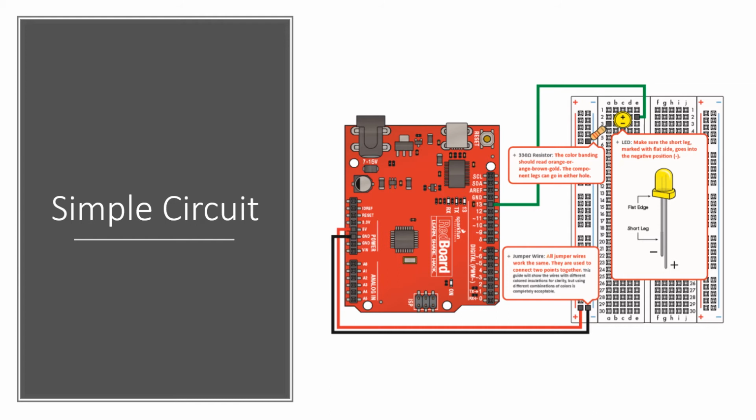All right, the power goes out through pin 13. Each of these is essentially a pin you can put wires into. I know from looking at the source code for the circuit that power comes out through 13. It comes up here through the green wire, and you see it's going into E2. And then this LED, remember, light emitting diode, is plus and minus. That one is in D1, so the power goes from E2 to D2 because those are connected. And then it's connected over here on the other side at B3.